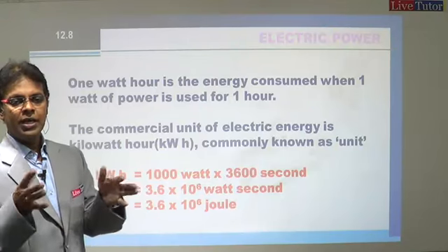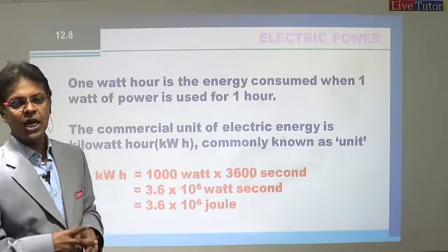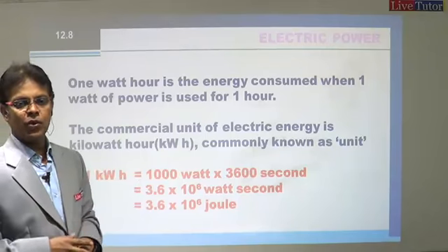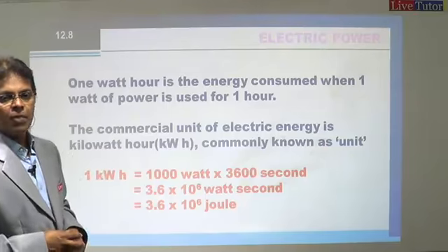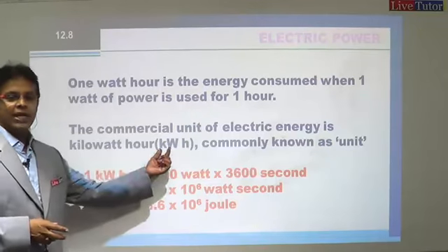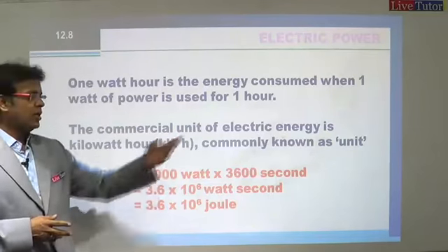Or 10 bulbs of 100 watts glowing for 1 hour is also 1 unit. That way we calculate the commercial unit, called kilowatt hour, kWh, usually called a unit.